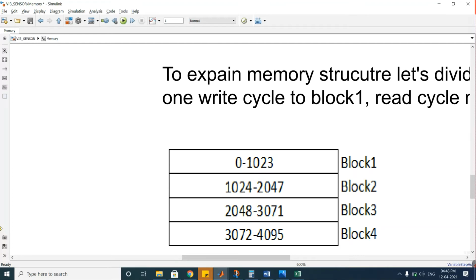The write cycle is writing to the 0th location of the dual-port memory. The read cycle starts from location 1025, goes up to 4095 and rolls back to 0. By this time the read cycle has acquired 3072 samples from memory, and the time taken to complete this will be 76.8 milliseconds. At this time the write cycle will be writing to the 768th location.